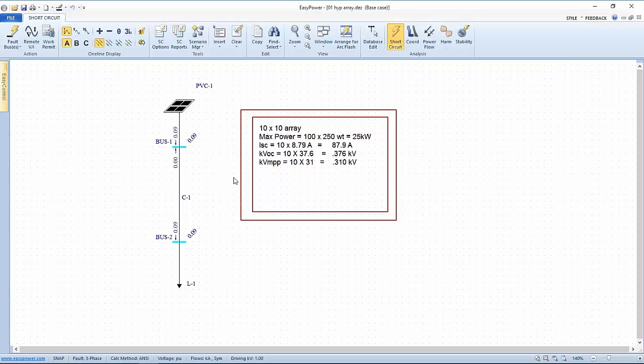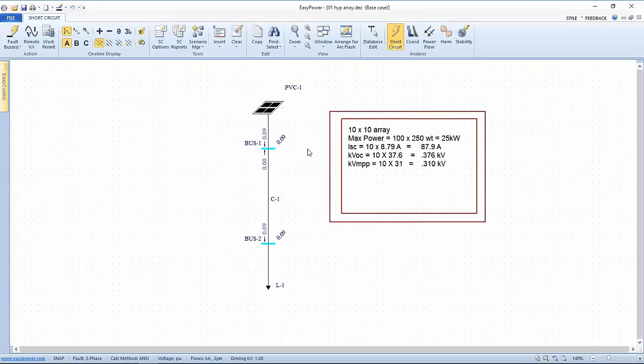And this actually brings up an issue I had last week when I was talking about the VFDs. When we have a low current such as this that may not trip a protective device, it won't necessarily give us an arcing current or an incident energy calculation on any bus. So in small systems or in segments of systems where the current is this low, we may not see calculated incident energy.